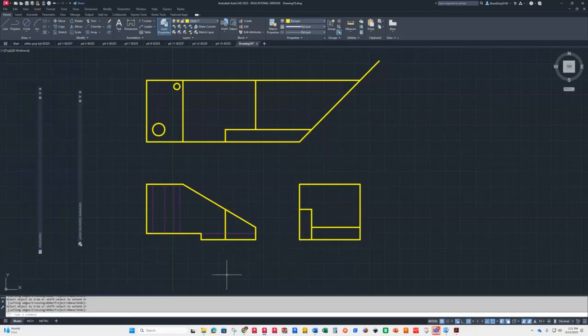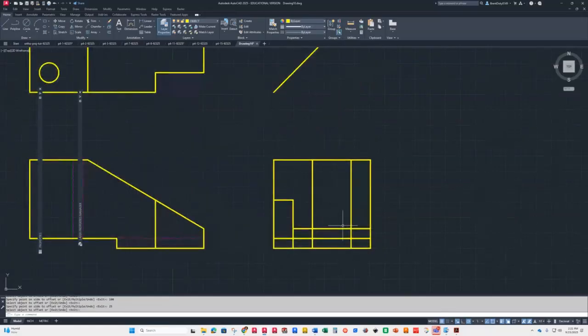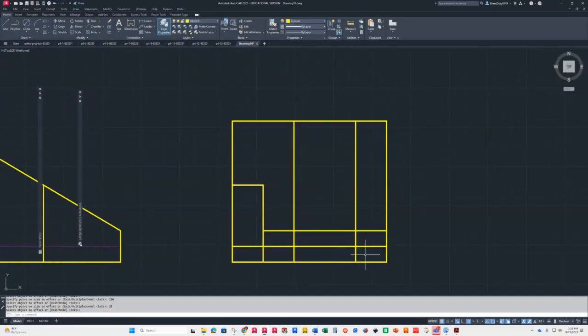And that. Okay. All right, last thing we need to do before we put in the holes over here would be this notch. And it says that it comes 50 off of here, so we're going to offset 50. And then it comes over 100, so we're going to offset over 100. And it's 25 tall, so we're going to go up 25. And then we're going to trim it out.